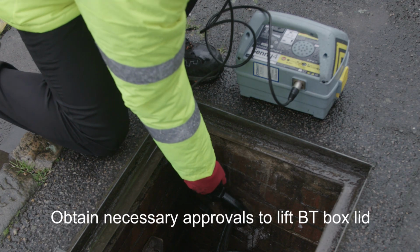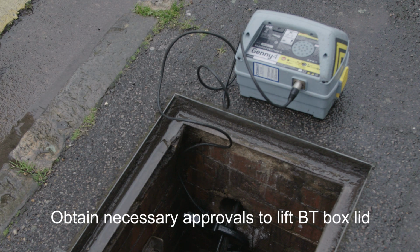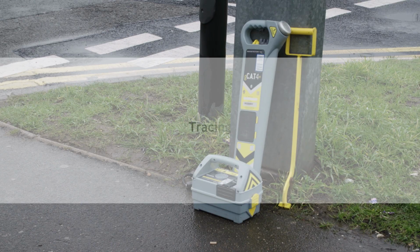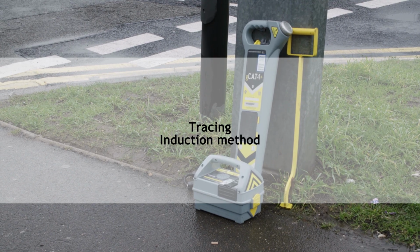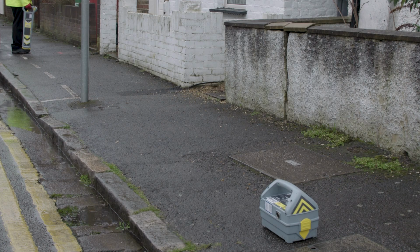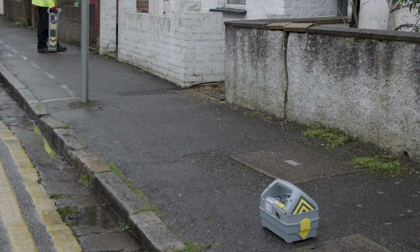Using the signal clamp to amplify a signal directly onto communications cables is the preferred method. Once connection and clamping methods have been exhausted, the induction method of the Genny should be used.